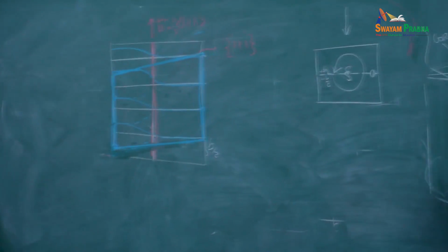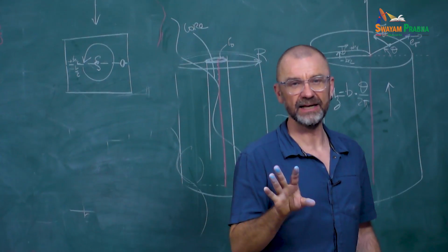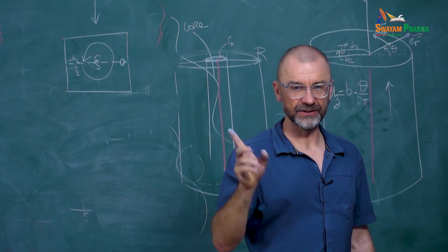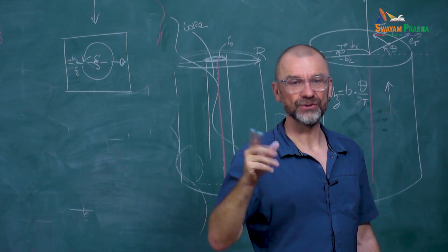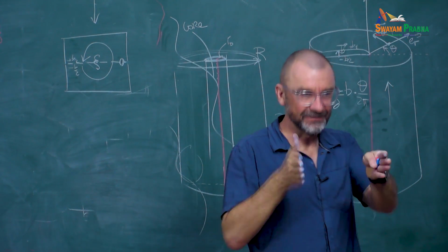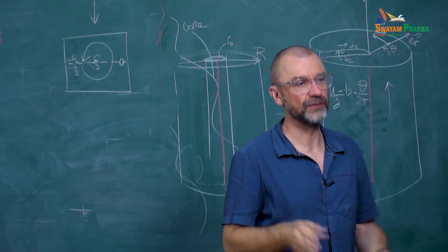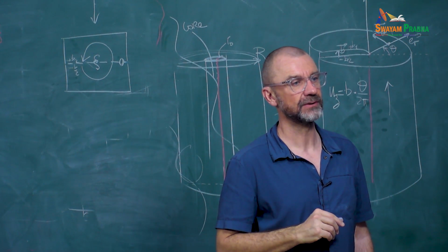So, yes, there is an example, but for BCC dislocations, not today. Today it's only edge, but there's an example tomorrow maybe. Yeah, day 3, with a screw dislocation, and you can look at the simulation cell, and you see that I've added a shift of b over 2 for the screw dislocation to reconnect the boundary conditions.